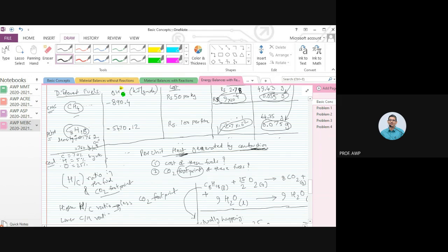And the calorific value, so lower calorific value, is, let's say, 5000 kilocalories per kg. We are not even worried about whether this coal is wet or not, whether it contains sulfur or not, whether it is going to contain ash or not. We are only going to look at the combustion. The calorific value is 5000 kilocalories per kg. Okay. Can you work out the CO2 footprint? Can you work out the cost?